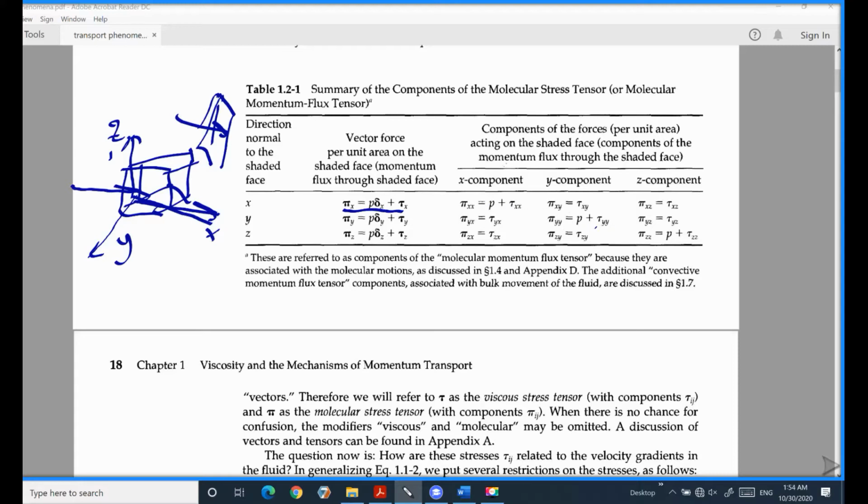We just have the pressure here, because pressure has to be perpendicular to the surface; the others don't. Similarly in the z direction for the x, y, z components, and we have the pressure term here, so we call this the stress tensor, with 9 elements.